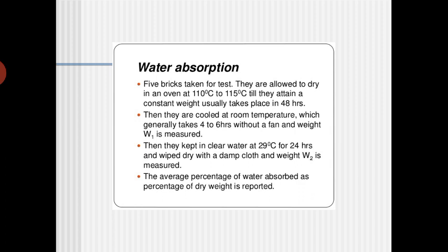Before proceeding, whether it is clean water or mud water, if it is mud water you are not supposed to use it, because mud water always contains organic matter. This organic matter is very dangerous. When it enters the brick, disintegration is going to happen. To prevent this, we will not use any mud water for the immersion.